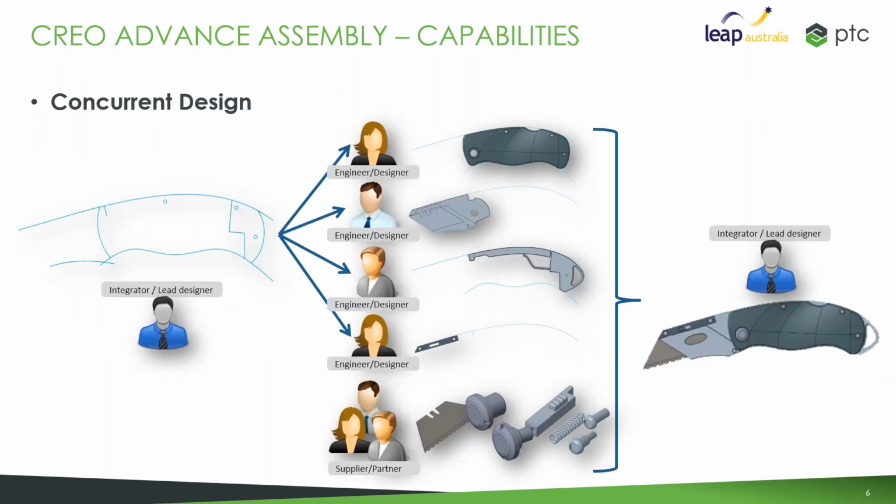Once you add this critical geometry information to the skeleton model, the next thing is the collaboration to share the geometry as references to build the component features. Published geometry and copy geometry are the two main data sharing features that Creo uses quite often. Once the model is activated, the publish feature enables the designers to identify and collect a selection of references from the skeleton and apply them to a feature. These references can be things like surface sets, curve chains, and references, or even datum features.